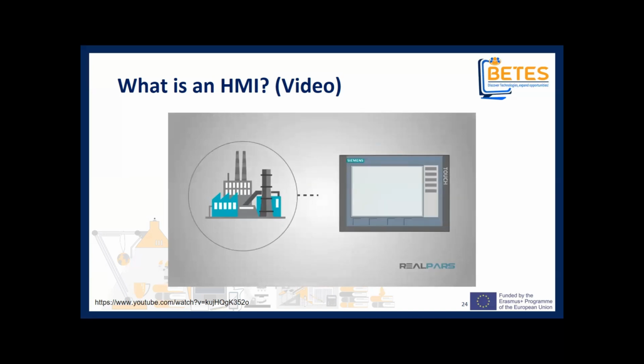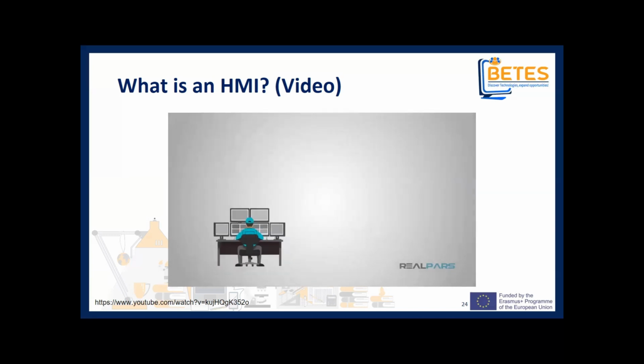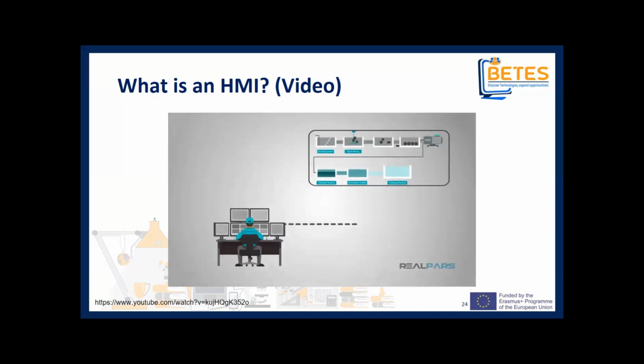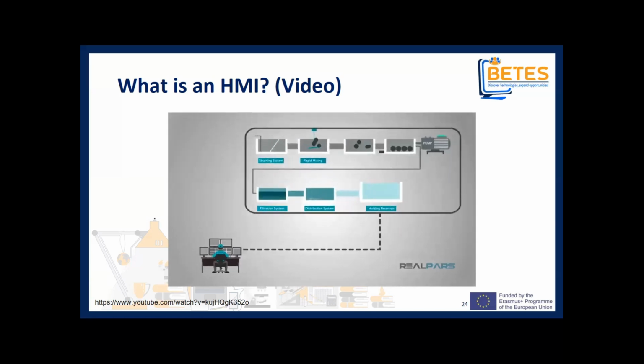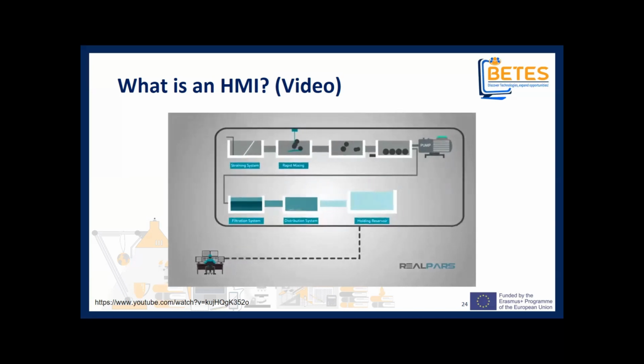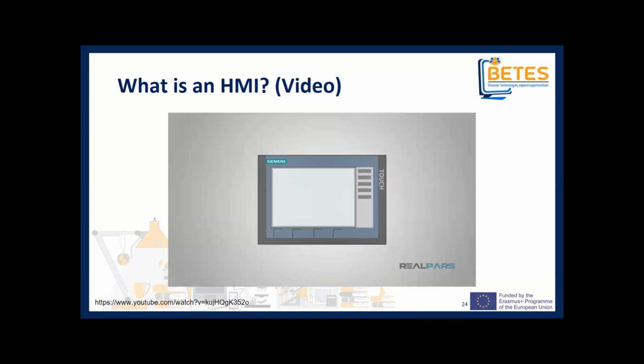A small manufacturing facility could even monitor the entire plant on one centrally located HMI. Water and wastewater facilities have utilized this for years by coupling an HMI with a PLC. They are able to monitor remote locations like water pumps, as well as equipment inside the plant. You probably get the idea now that an HMI is the operating panel and monitoring screen.